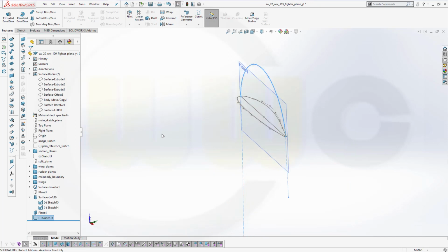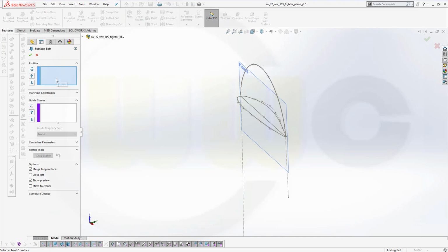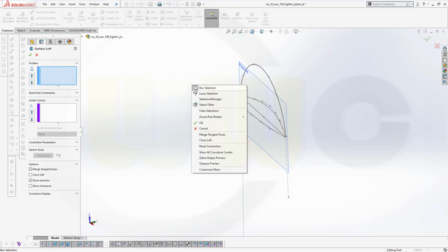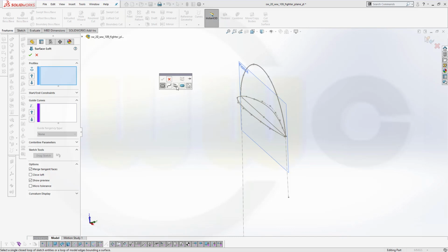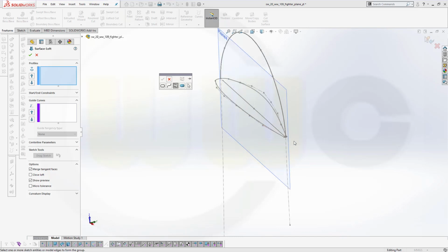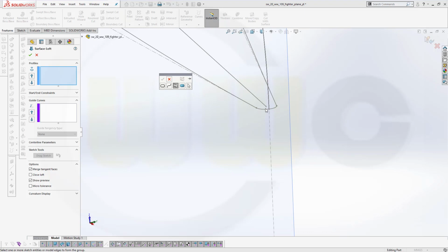And now I want to go for lofts because the fills will not work, I suppose. So I don't need the surface. I could do it with the sketch because I went normal to the profile and I go normal from that profile, so that will do. So let's go for a loft and profile. I want to use a group, and the first group would be just that arc.